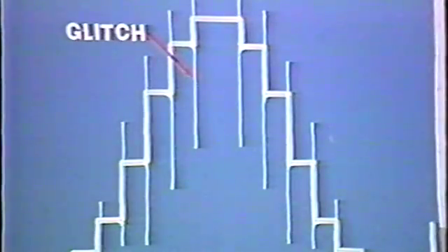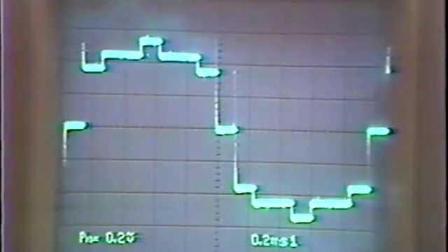The stepped waveform output by the digital to analog converter enters the sample and hold circuit. This circuit eliminates noise called glitch noise included in the stepped waveform. A thin noise appears in each of the steps of the stepped waveform output by the digital to analog converter. This is called glitch noise and is the cause of high-frequency noise. This is the glitch noise.